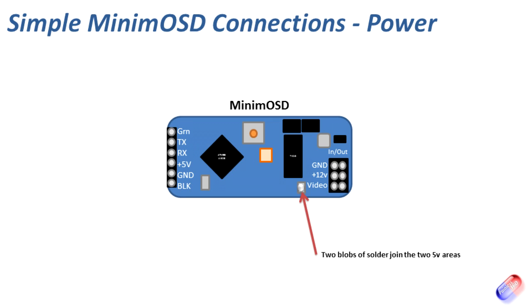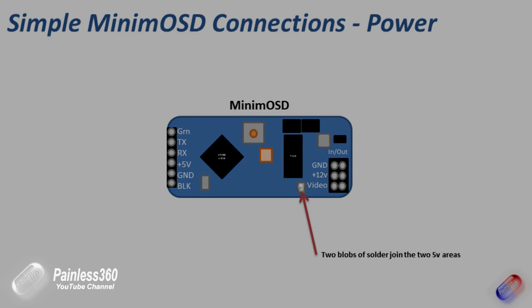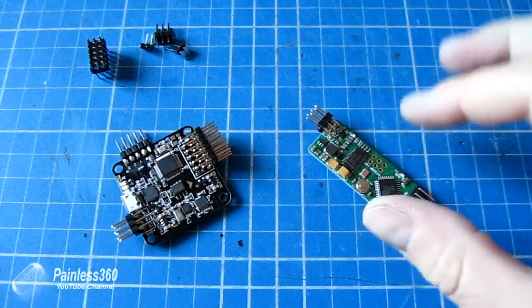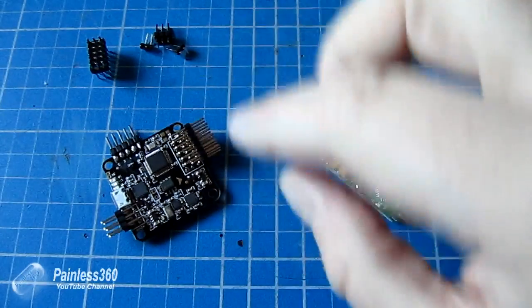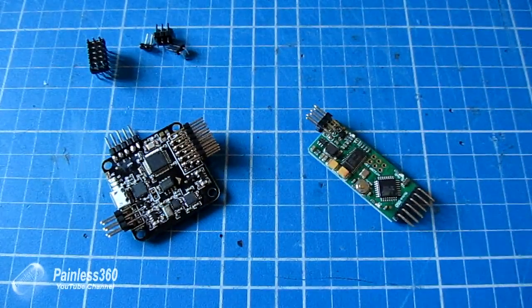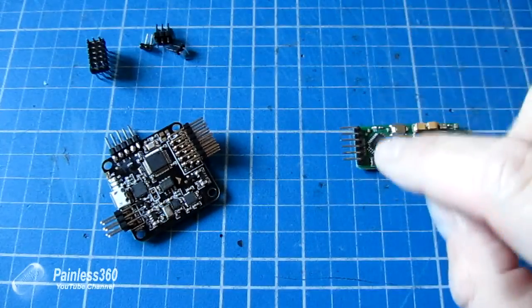We can move on to the next part and talk about how we're going to connect the board to the Naze32. The thing you have to do here is solder two additional pins into the center of the board. Now, we didn't do this in the initial config and setup because I thought, to be honest, the MinimOSD would want to be later videos, but it's one of the first things that's arrived in the post.